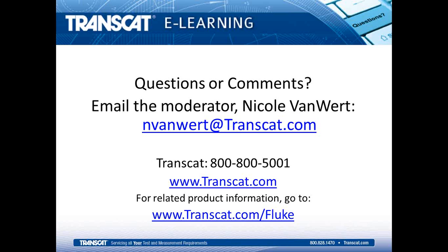So the last question, if the inserts get stuck in the calibrator, is there something I can do to try to remove it? Yeah, good question there. I've had plenty of experience back in my days with service trying to remove stuck inserts, and depending on the situation, they may or may not ever come out of there. You can try a little bit of WD-40, let it soak down between the seam and the insert, but I would certainly recommend that you just do small amounts over a period of time, and then try to use that to break it loose. But it's possible that it's stuck for good.